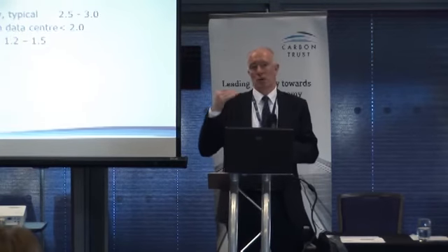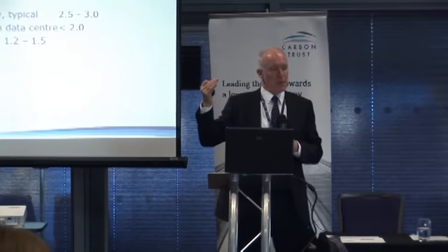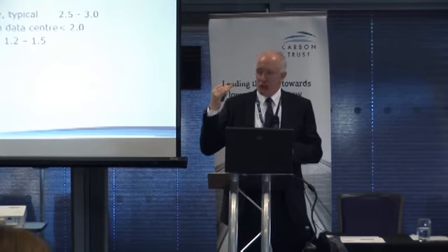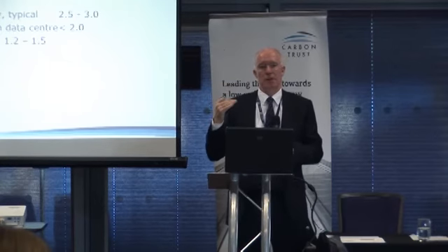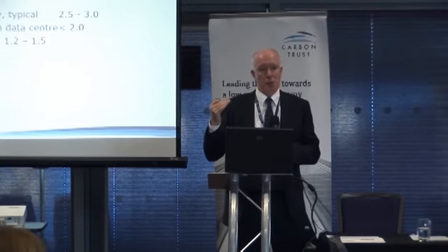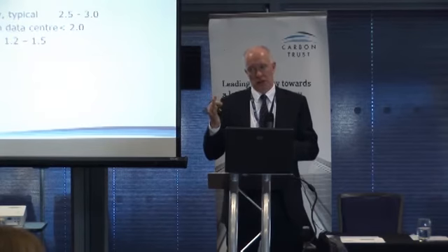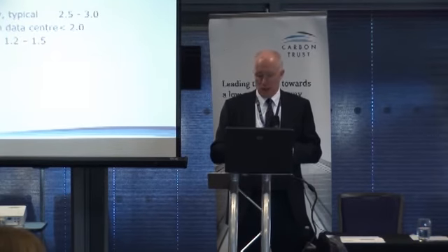So you'd expect, with the COP of refrigeration, to go to about 1.3, 1.4. But in addition to that, you've got all the fan power, the motive power associated with moving the air and moving the water around. You've got all the lighting heat gains, and all of the ancillaries that come into that computer center. So that's typically up at about 2.5 to 3.